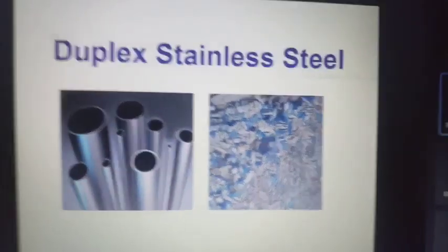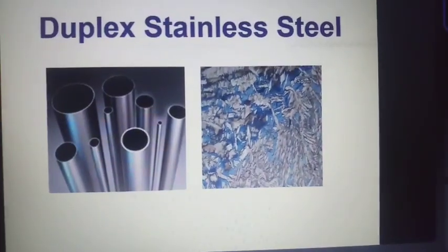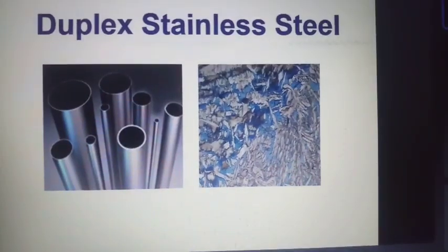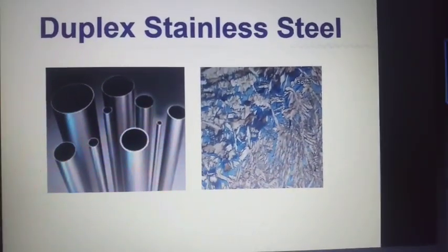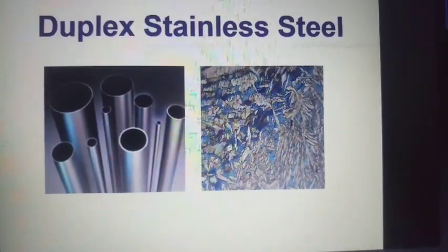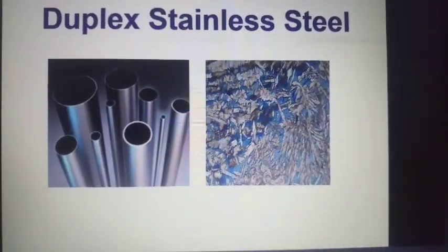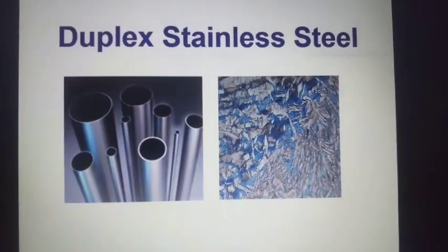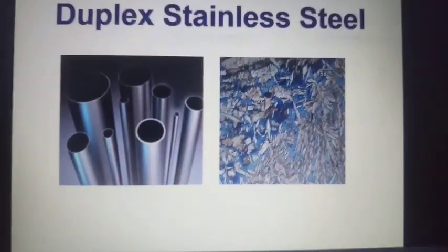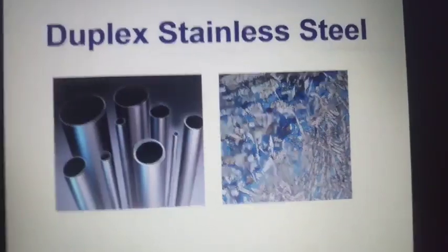Okay, first thing. Second thing is that the first is the preheat you control, or the interpass also you control. You lower it so that it cools faster. Weld the smaller beads for the higher grades, high carbon grades. Weld the smaller beads so that you will have a lower heat input. Then the cooling rate will be faster. So the welding process we need to select is such that your cooling rate will be faster.